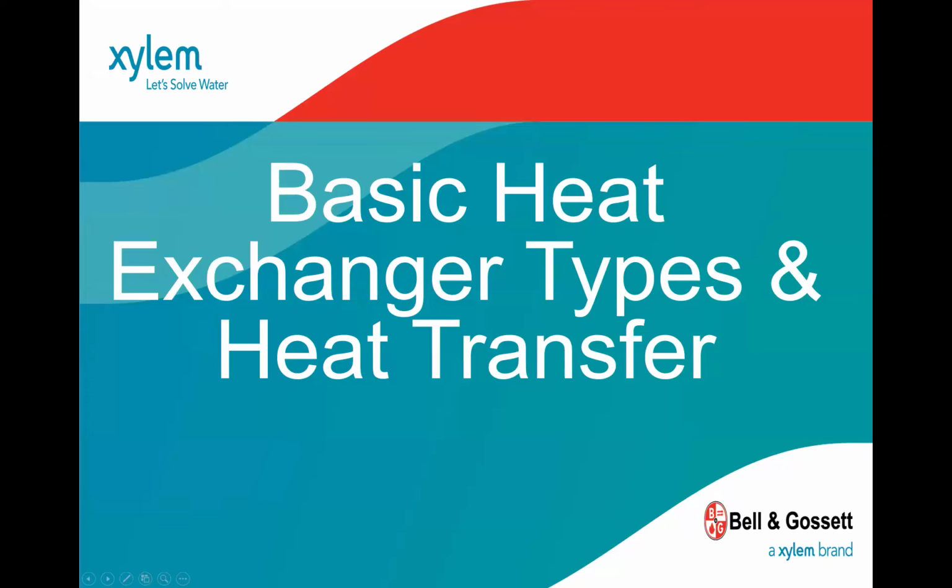You'll notice a lot of the selections across the industry, just so people are familiar, is that about every device out there, whether it's from boilers to heat pumps and chillers, there's usually third-party testing. Now, for heat exchangers, specifically the plate and frame style heat exchangers, there's what they call AHRI Standard 400.